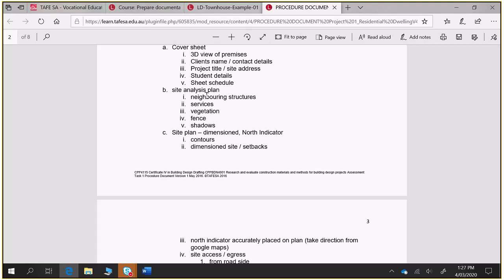Do we actually have to show the solstice and different times of the year? Yes. It can be on the same plan if there's one particular time which is going to be an issue. You can make a decision about, okay, at this point in time, it's an issue, or at this point in time is what the council and the neighbours will be concerned about, and you want to show that at that point in time it's still not an issue. Or if it's just a general thing, then you do summer solstice, winter solstice, and equinox, to show the two extremes and then what it's like in between.